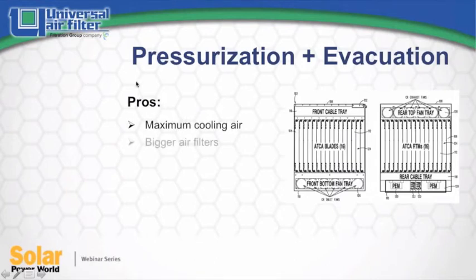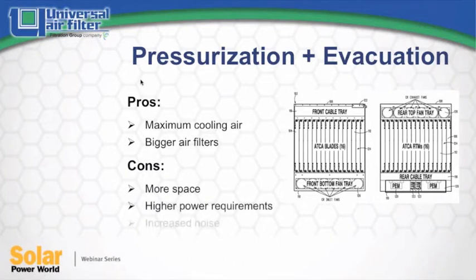Fans on both the intake and the exhaust ends maximize cooling air and allow for more dust holding capacity. Unfortunately, you need to make room for more fans, use more power, and more fans usually means more noise.